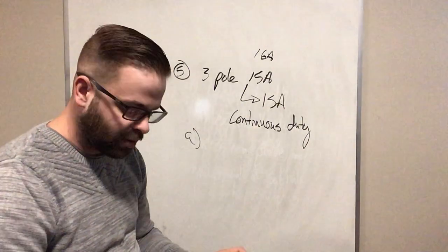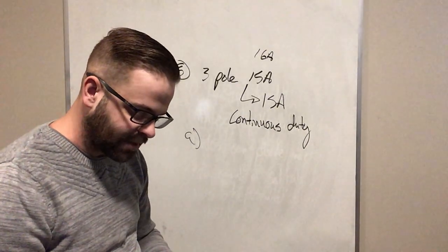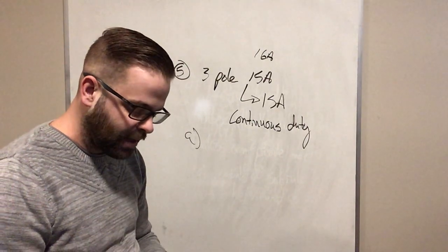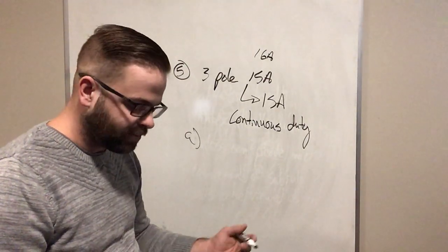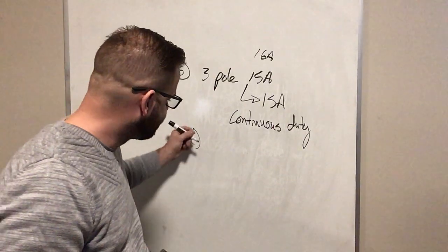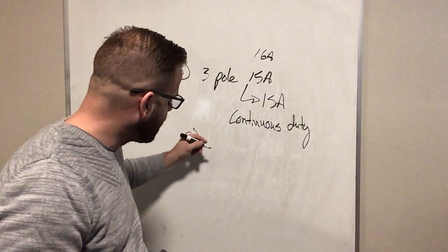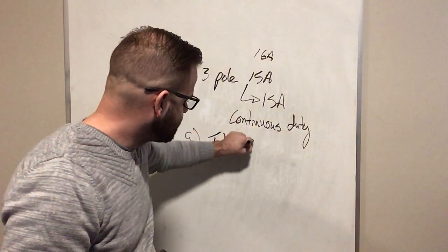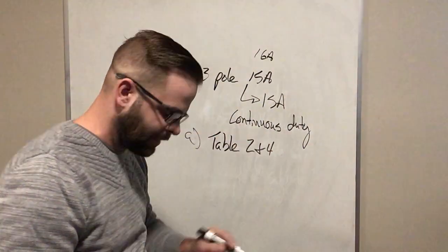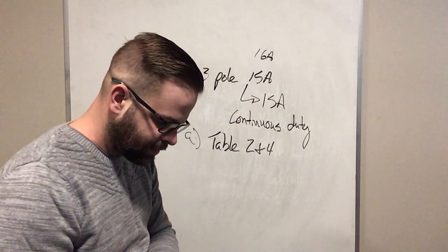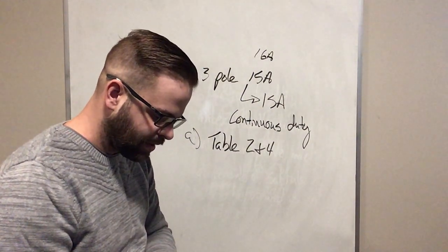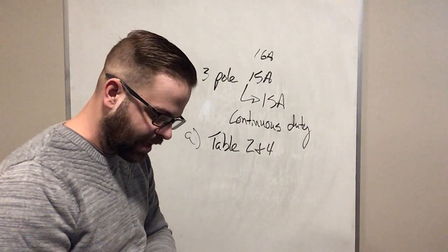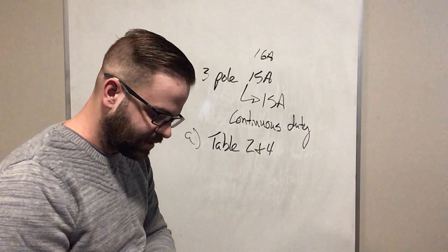So what they're determining there, and because it says allowable ampacity of conductors, those would be multiple conductors. So it's referring to wire that's been sized based on table 2 and 4. And so it says, except as required by item B, shall not exceed 100% of the allowable ampacity of conductors selected in accordance.